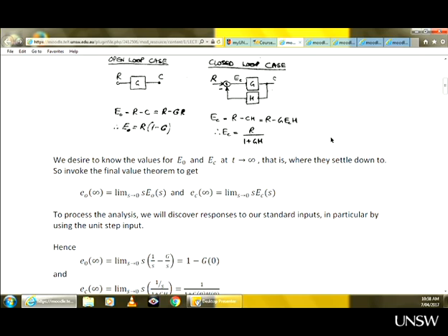Is this a linear system? It's very non-linear. You can try to linearize it and derive a transfer function, but it is a feedback loop system. It is negative because it has this sensor that controls the valve. If you're getting higher temperature, it reduces the intake of hot air. If the temperature is low, it increases the intake of hot air. So it is an example of a negative feedback control system, but linearity is really questionable.